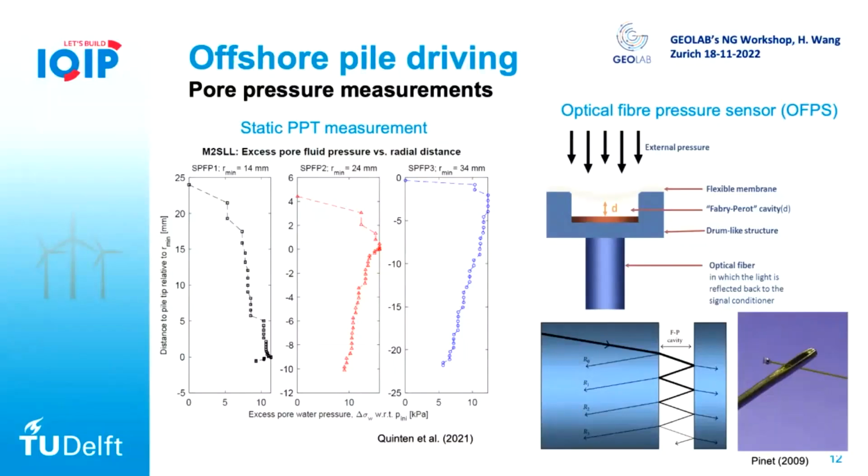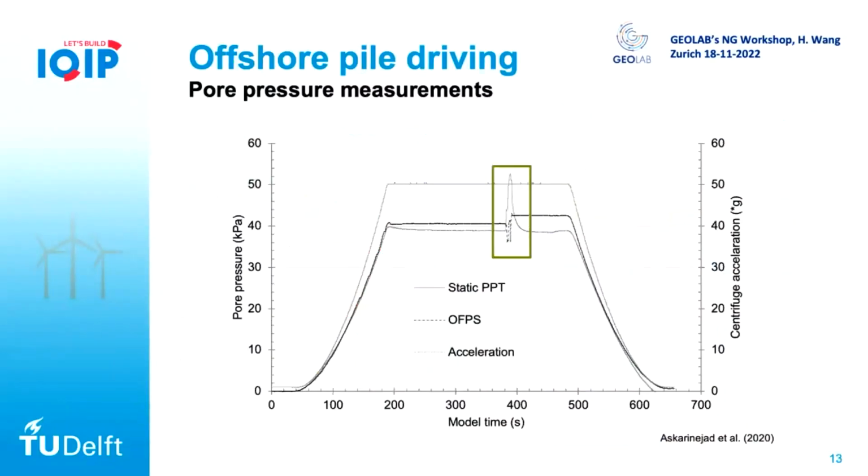at the interface. And if you look at the results in the next slide, you can see we plot the response from both the optical fiber and the traditional pore pressure sensor. And during the acceleration of the centrifuge in the test, after the centrifuge test, you can see the optical fiber can really capture the pore pressure response.